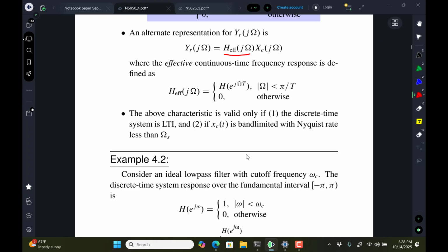You've already characterized the audio codec, I think, right? It runs very close to the folding frequency and then it just drops very, very rapidly. It crosses over a tiny little bit. And I think there was an experiment you did where you listened and you could hear it actually cross the folding frequency and have a slight dip in pitch, and then all of a sudden the amplitude, it's gone.